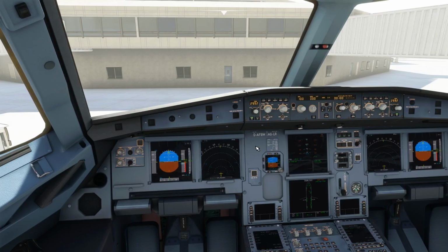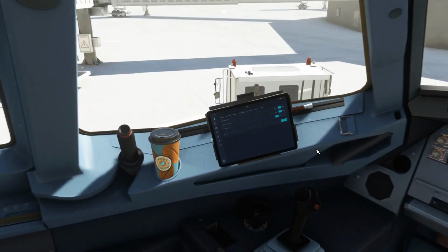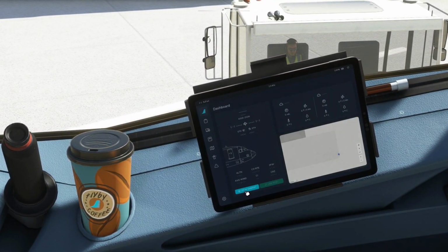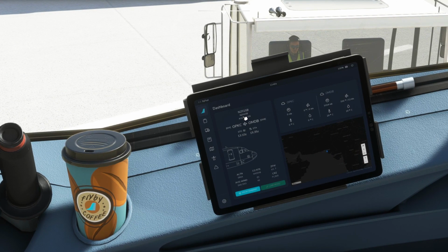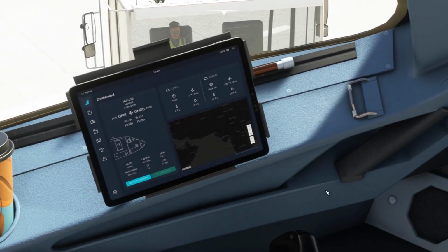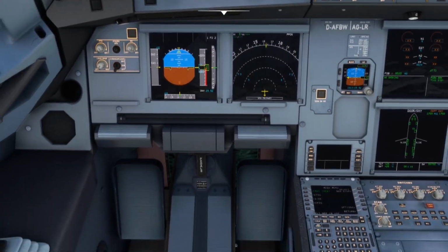over here in the cockpit and do one thing. Go over here in this option and get the flight information from the SimBrief. Now you can see that it's updated. OPKC to OMDB. Alternate is coming. Zero fuel weight is given. Average wind. CI, cost index, is 42 right now. I'll tell you later what the cost index is, and the cruise altitude is flight level 360. That's 360, that is 36,000 feet.